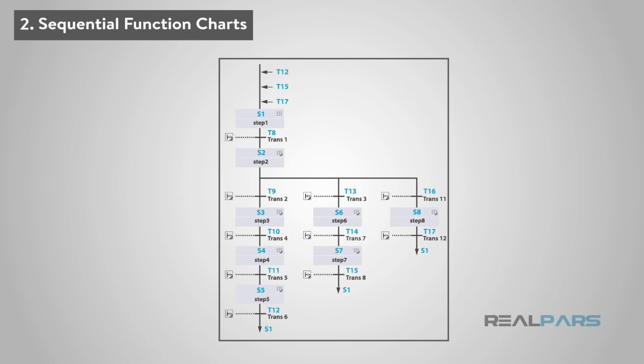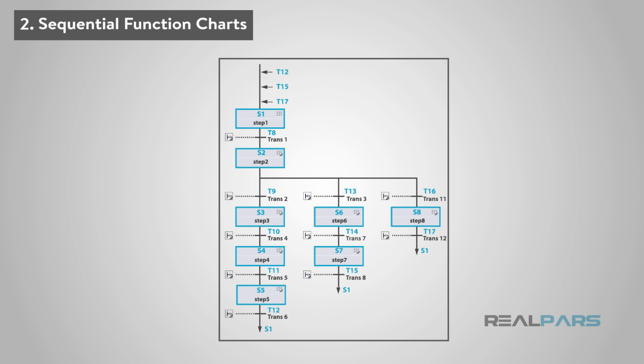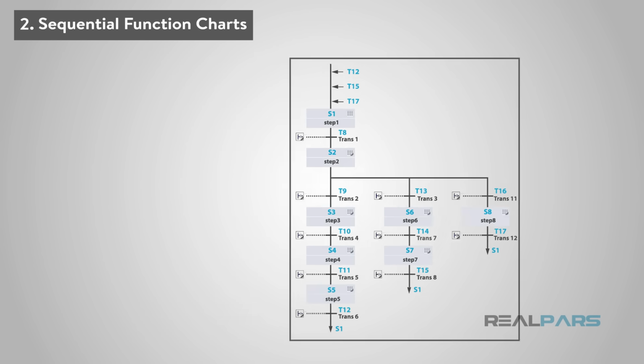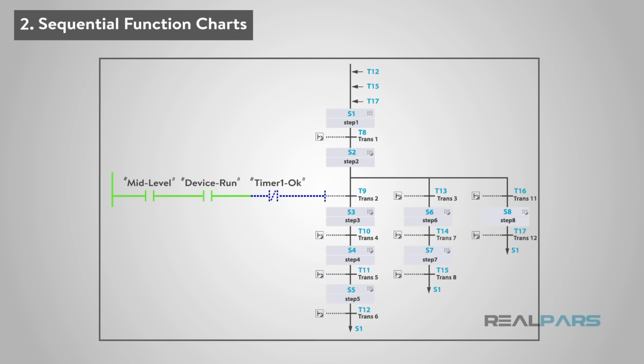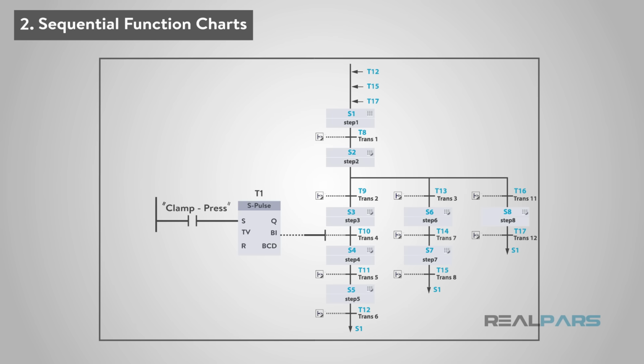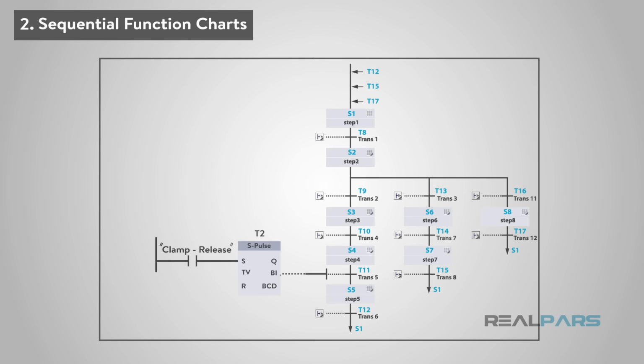A couple of the advantages of sequential function charts are: processes can be broken into major steps that can make it faster and easier troubleshooting. You have direct access in the logic to see where a piece of equipment faulted. It can be faster to design and write the logic due to the ability to use repeated executions of individual pieces of logic. Even when you consider the advantages of the sequential function charts, this PLC programming language does not always fit every application.